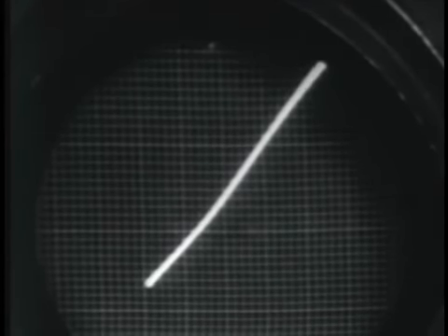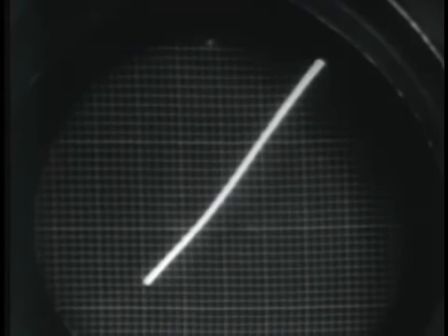So the width of this oval would denote a phase displacement of 22.6 degrees. And we have ER with respect to EA here. Let me show you this one real quick. This would be two sine waves in phase, would it not? So somewhere between in phase and 90 degrees, we have an oval like this. And this oval, as I said, would represent our phase relationship of ER with respect to EA.